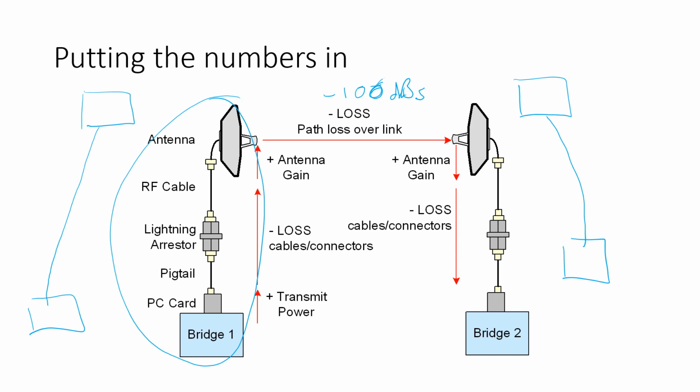So you don't need to worry about these separate bits and pieces. Now, if you inspect the link for the antenna, you'll find one or two useful bits of information. You'll find that the transmit power will be easily within the UK specifications, so let's choose the UK maximum transmit power of 20 dBm. Of course, from a regulatory point of view, we might need to rein that power back a little bit.